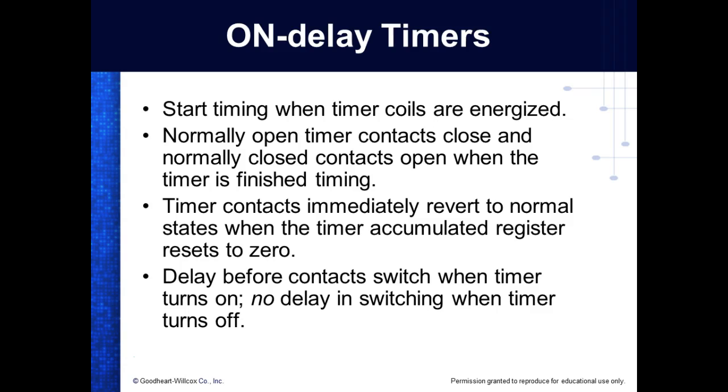If you buy one of these, you're dedicated to what's in there, right? Solid state timers usually have very few contacts. They might have one normally open and one normally closed. So on a solid state timer, if you need a bunch of contacts, you're going to have to run it through a control relay that has a bunch of contacts.